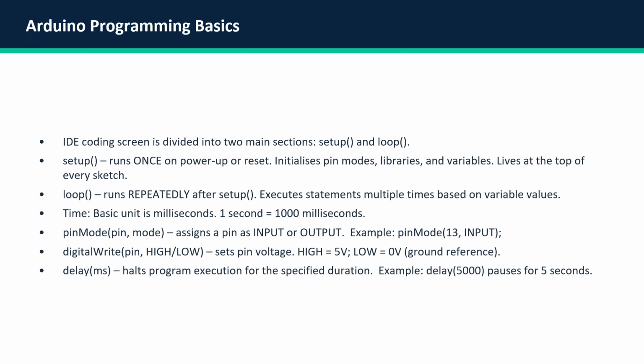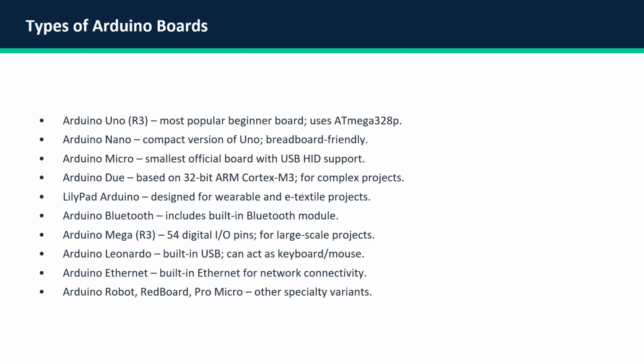pinMode assigns a pin as input or output. digitalWrite sets pin voltage. Delay halts program execution for the specified duration. Types of Arduino boards. There are so many Arduino boards. These are some of the types.